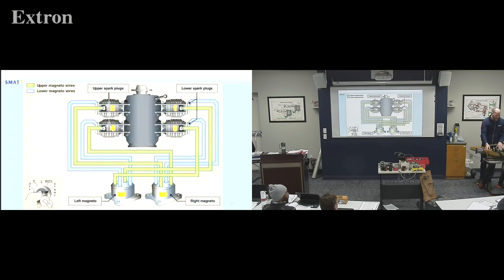Once it gets to the bottom, we go to the second stroke, which is up, and the intake closes. The exhaust is still closed, so now I'm just compressing all that air and gas so that it's a very high pressure. So that's stroke number 2 on the Otto system, the compression stroke. Now, here's where it ties into this class and why you need to know.